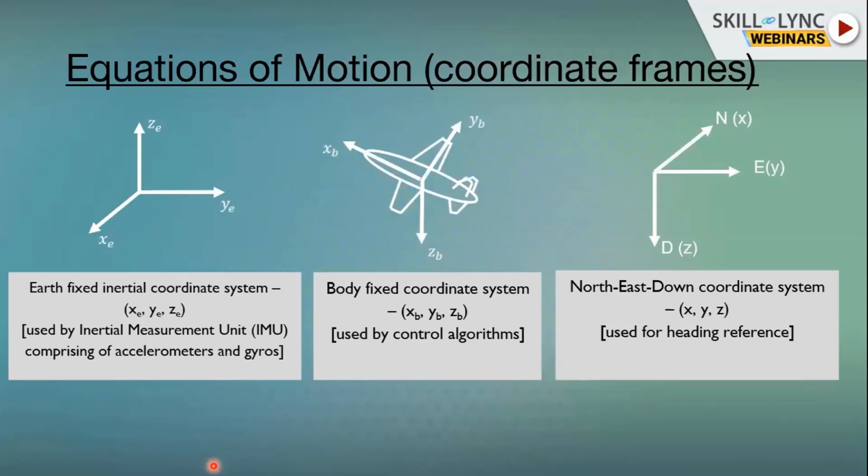That's where the body coordinate system comes in, where the velocities are measured, or the accelerometers measure the body accelerations, while the gyros have always had the inertial frame reference, so they are doing the bookkeeping on what the aircraft is undergoing, and keep integrating.